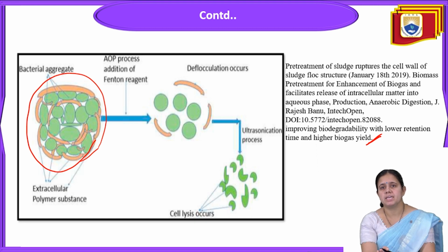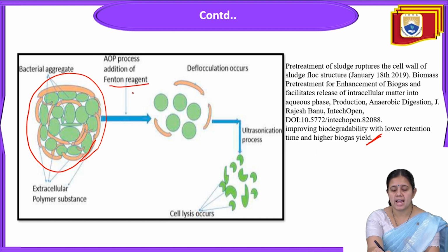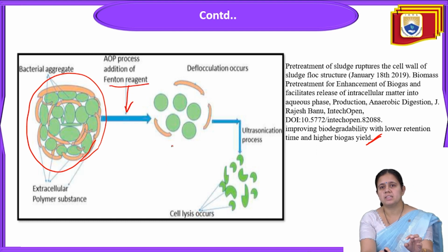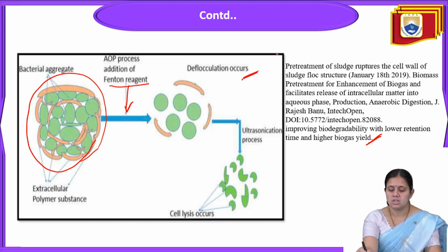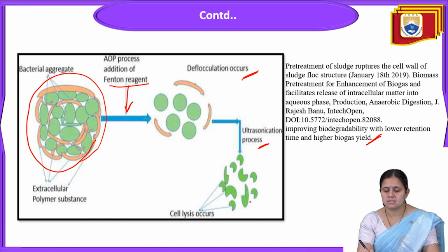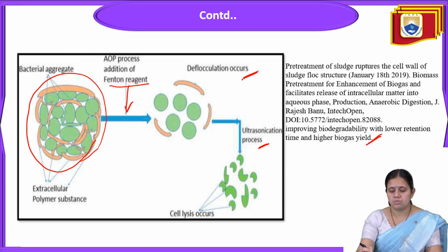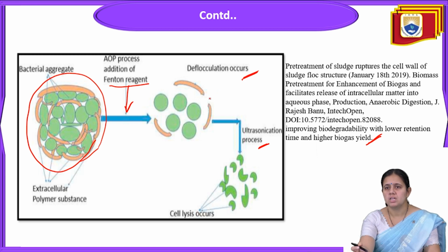When the AOP begins, we add Fenton reagent to the process, and because of this Fenton reagent, deflocculation occurs. The Fenton reagent breaks down the floc, and deflocculation occurs. Next, the ultrasonic process follows. This ultrasonic process breaks down the cells, which is called cell lysis.